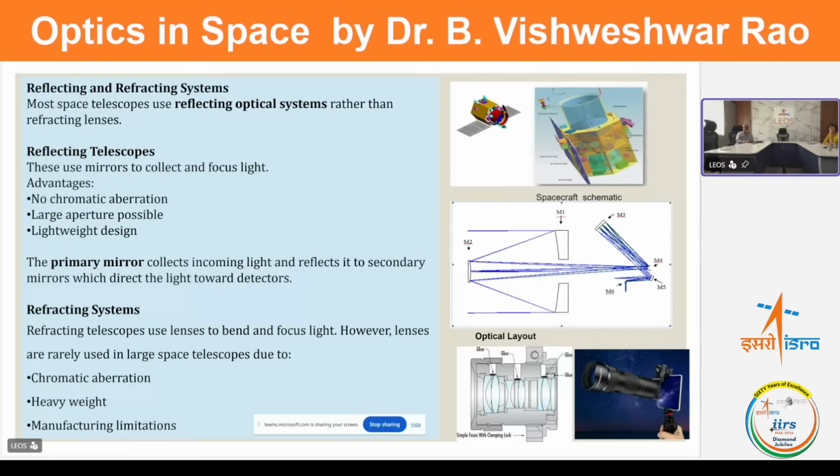So in the primary mirror, you can see a depiction shown here. This is the particular configuration of a telescope where you have a bigger primary mirror. Let us say it is 1.2 meter to almost 2 meter size, and we need to have a thick blank. When you go for thicker blanks, the weight of the telescope and the weight of the spacecraft carrying it will have expenses which will be charged by launching agencies. So the general procedure followed is that these mirrors will be lightweighted.